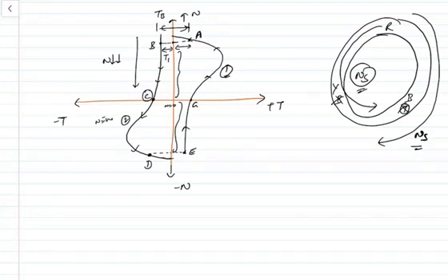That means by changing the phase sequence, the direction of the motor can be changed from one mode to the other mode. Intermittently, for some time, it will operate in the braking mode, because here also it operates in the braking mode. During that time, heavy power loss will happen because this entire power is lost in the form of heat in the induction motor. Why in plugging the power is lost in the form of heat and other things, I have explained in the circle diagram.